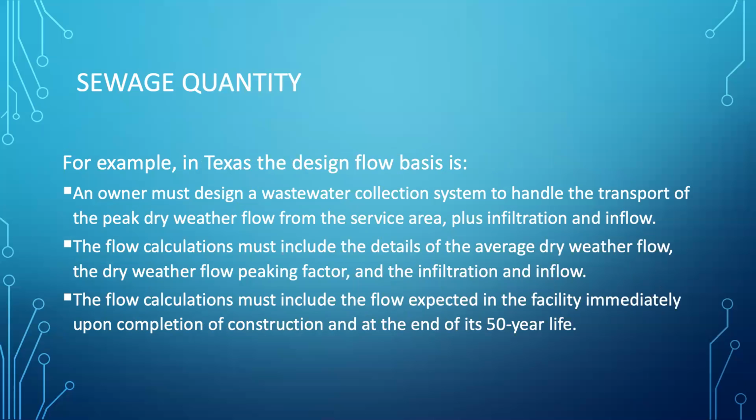So in Texas, design flows are based on a variety of techniques, and they're provided because the owner must design a wastewater collection system, and the Texas code specifically says to handle the transport of peak dry weather flow, and that's defined in the code, from the service area, plus infiltration and inflow.